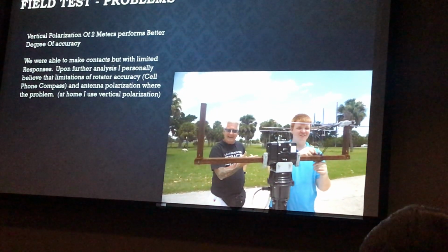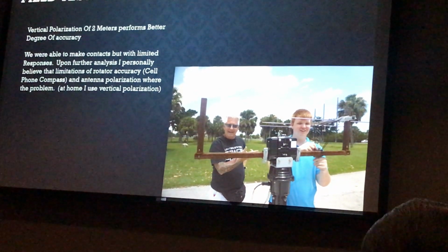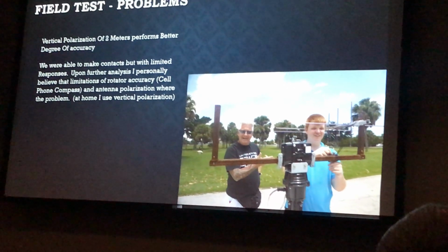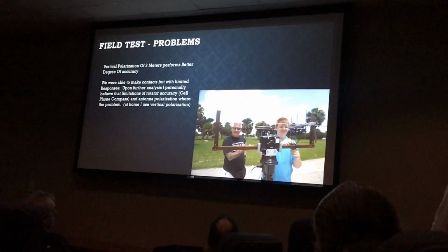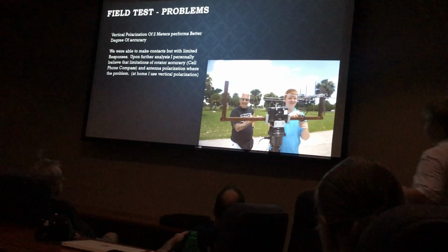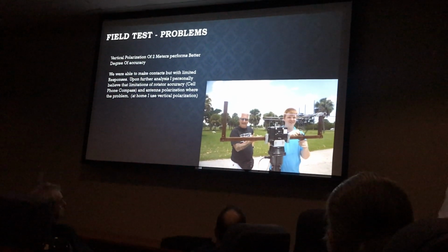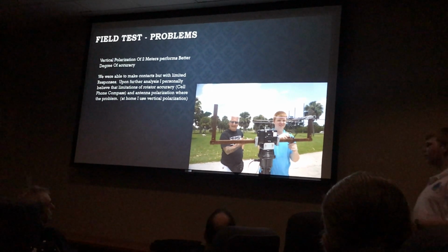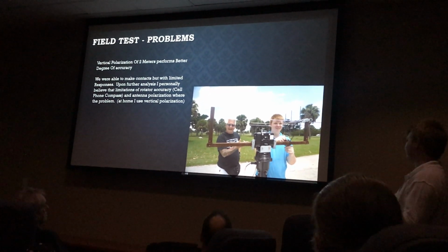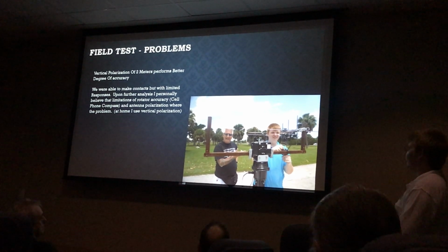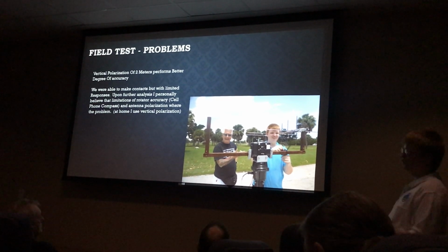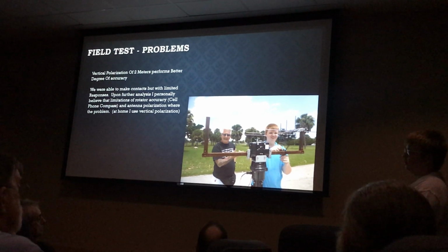Now 0 degrees is here. And every time you spin around, 0 degrees is a little bit somewhere else. So I would say that was the main problem there, is that the rotator was not calibrated to exactly 0 degrees north, and you can be a couple degrees off. I've noticed anywhere up to 4 degrees off, and it doesn't really have too much of an effect. But I would say we are at least 10 degrees off on the calibration.